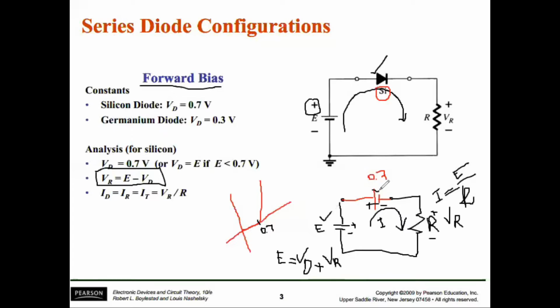Okay, so now you can see that this is the equation, because here this is voltage rise, and this is voltage drop, because if you consider this current, it is entering through the negative terminal and coming out of the positive terminal. Similarly, in this clockwise direction the current is moving into this positive terminal and coming out of this negative terminal, that's why this is the voltage drop. Similarly, across the resistor, it would always be a voltage drop. So that's why we have written it like this, and from this equation we can calculate this one.